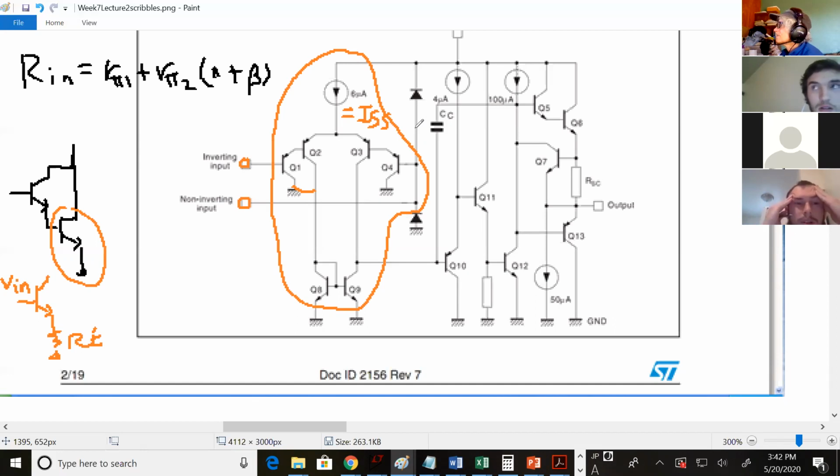Does that help your Rn be bigger? Maybe. That's exactly it. Think in equations rather than touchy-feely on this one. A voltage over a smaller current will be a bigger resistance than a voltage over a bigger current. Yes, and if you think of it equation-wise, it is over a current.